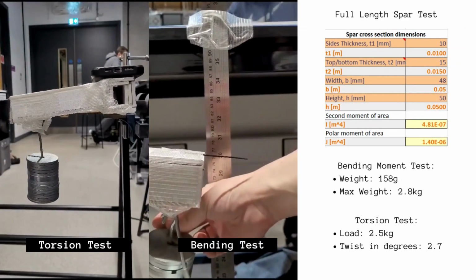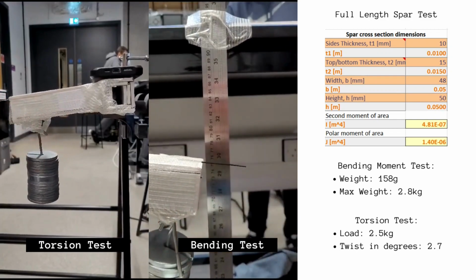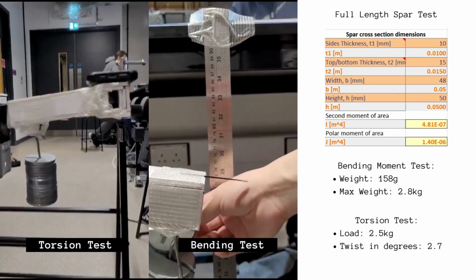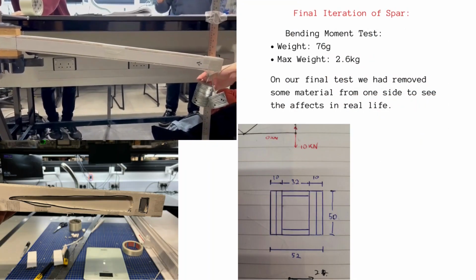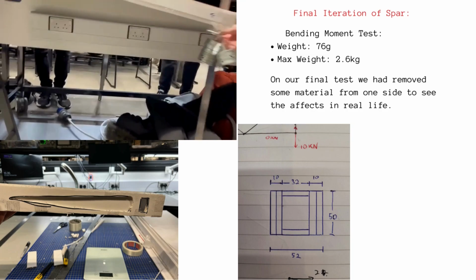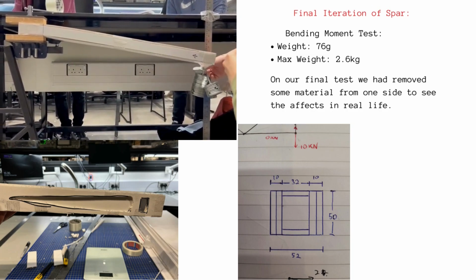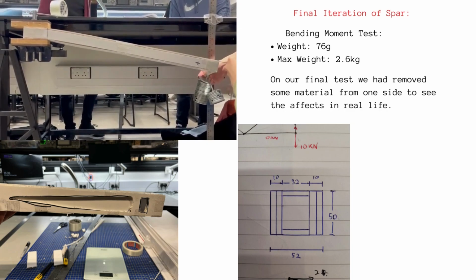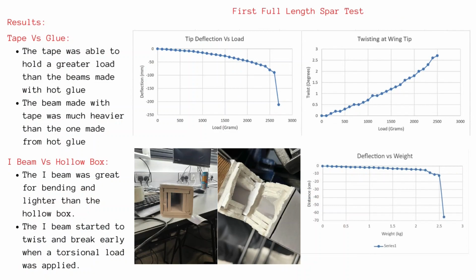For our first iteration, our beam met all the requirements we were given. However, the beam carried a greater load than was needed and was quite heavy. This would suggest that there was excess weight that was not needed. For our final iteration, we used a much smaller cross-section, and we also took some material from the side of our spar to reduce the total mass. This final spar managed to hold a load of 2.6 kilograms, which is just over the ideal load. As we are only using half the spar, the total spar should hold 5.2 kilograms.